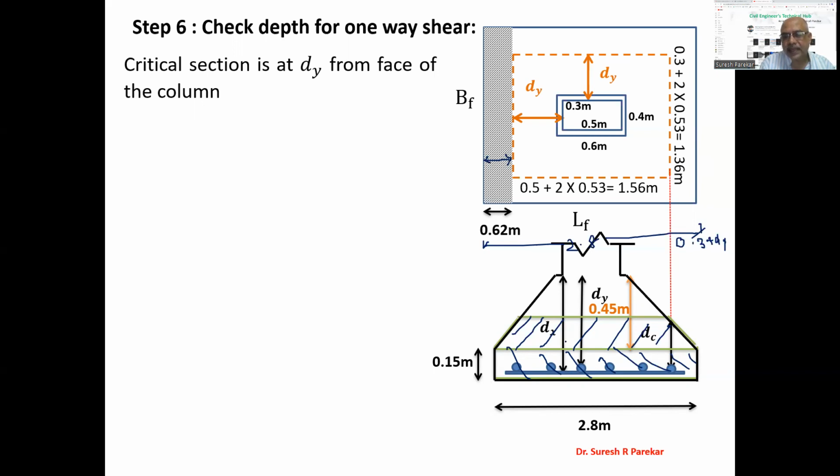So we have to find this area, multiply it by the permissible stress, and then check the shear force which will be developed by this hatched portion. So now we will go the same way. Now at dy we have to find this depth, and in the same fashion we calculate it. Again, till this 0.53, then 0.05 will be offset, so 0.53 minus 0.05 gives us 0.48. So we have y upon 0.48 and 0.45 upon 1.1.